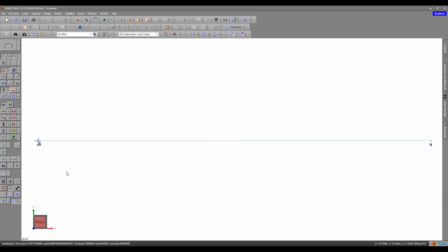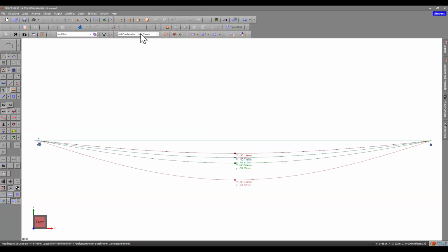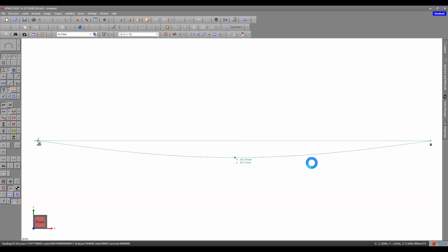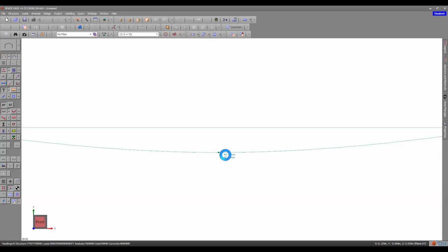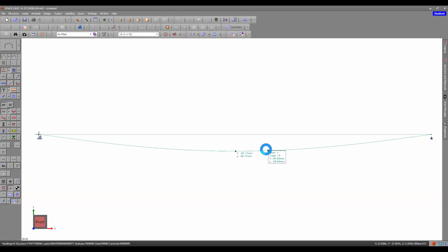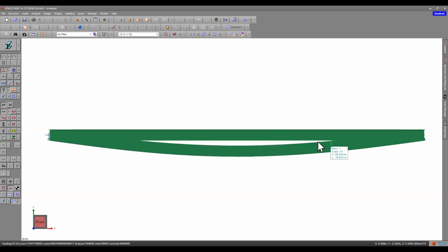The third one is the deflection. The deflection will only come from the load combination G plus psi Q. So don't use the deflection from the strength load combinations. As you can see here, how much is the deflection? It is negative 40.17 millimeter. This is the deflection, and this is the deflected shape if you want to show the render. This is the original beam location, and this is the deflected shape location. You can show it like that or like that.